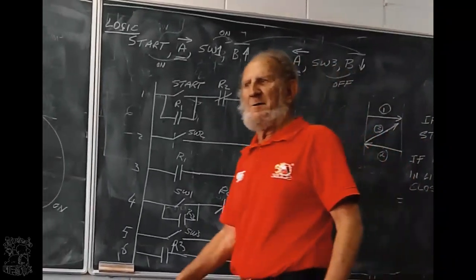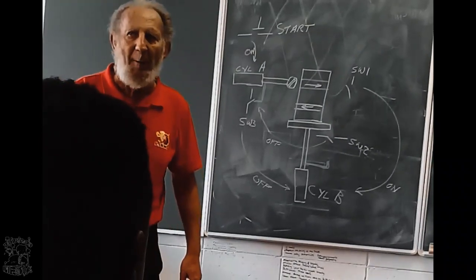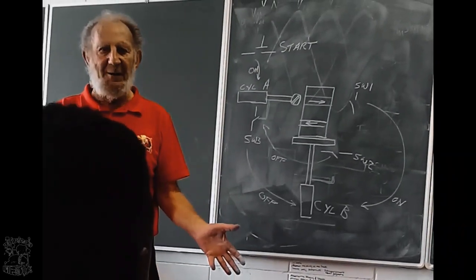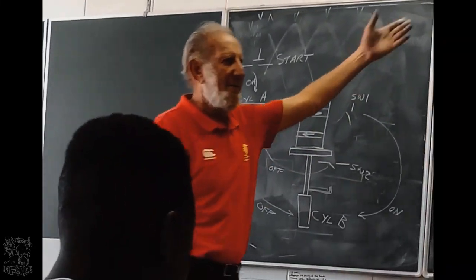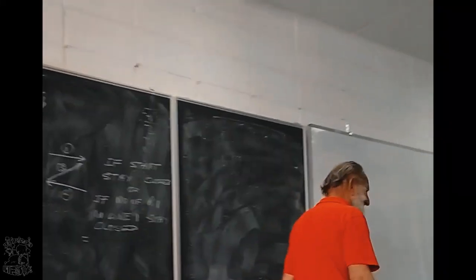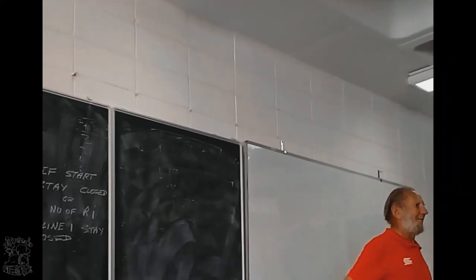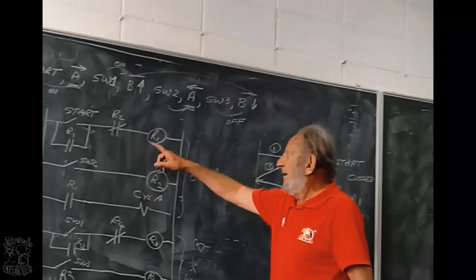That's what you see. What will happen if this opens and stays open? Then relay 1 cannot get power. So it will complete the first job. Next job cannot start, because you cannot put power on relay 1 again. It will complete the first job and the next job cannot start. That is if that stays open.